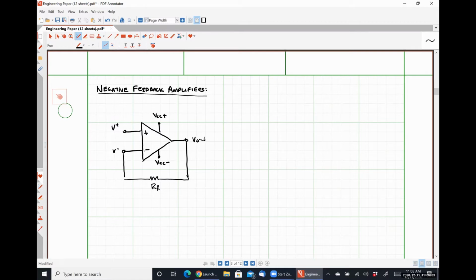But in a negative feedback circuit, what's happening is that the output winds up subtracting a little bit from the input, and so we don't see extremely large gains, right? So even though our op-amp circuit has an open loop gain of tens to hundreds of thousands to potentially millions, we should see that in a negative feedback configuration, we can drive that gain down to specific values that are actually useful for amplifying a signal, effectively increasing the linear range over which the amplifier operates.